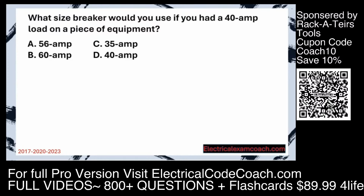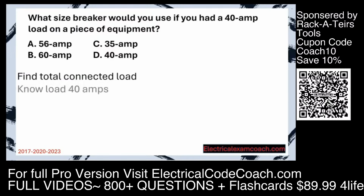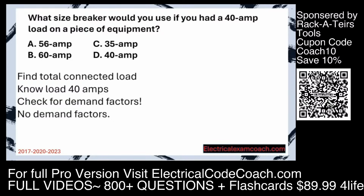What size breaker would you use if you had a 40 amp load on a piece of equipment? Step 1, find the total connected load. The known load right now is 40 amps, but we check for demand factors. And in this case, there are no continuous loads or specific piece of equipment. Therefore, there are no demand factors.